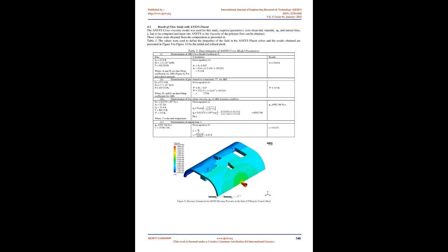τ equals natural time, the inverse of the shear rate at which the fluid changes from Newtonian to power law behavior. n equals power law index. γ̇ equals shear rate. The zero shear viscosity, η0, is given by equation 2.19: η0 equals D1 exp[−A1(T − T*)/(A2 + T − T*)], where T is the melt temperature, K. T* is the glass transition temperature determined by curve fitting. A2 equals A3 plus D3P, (3). P is the pressure, Pa.